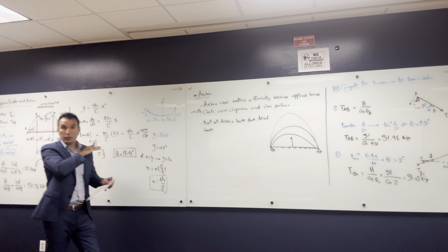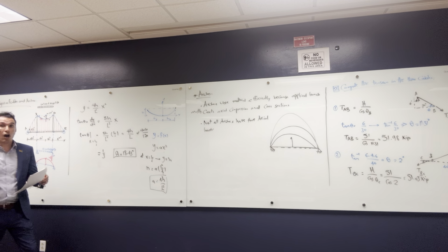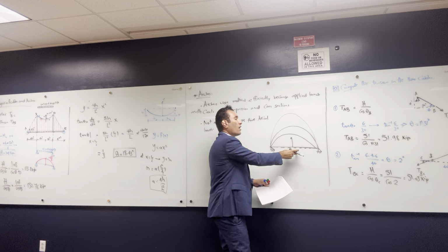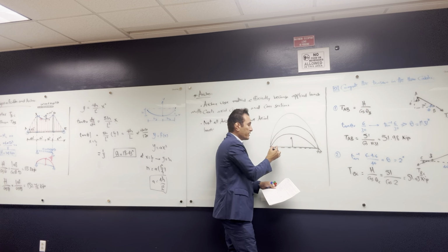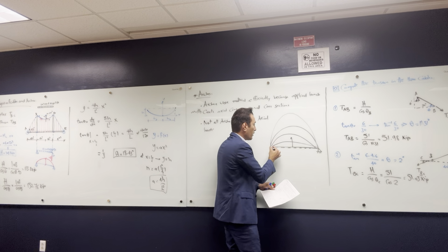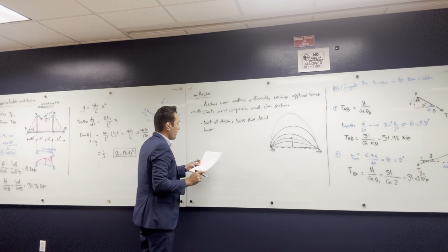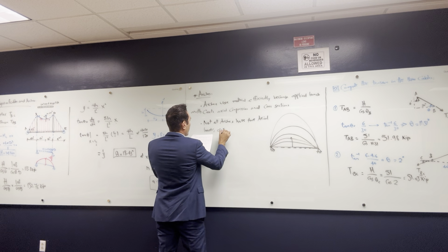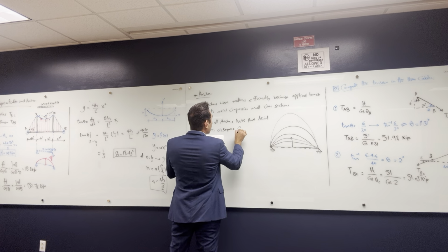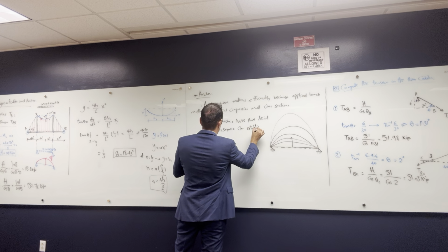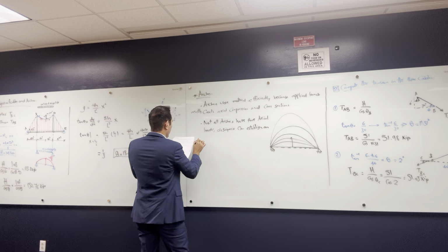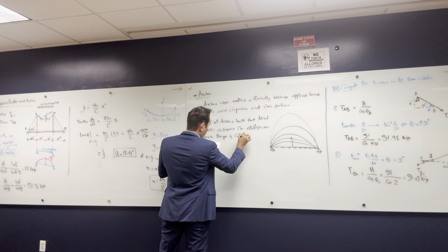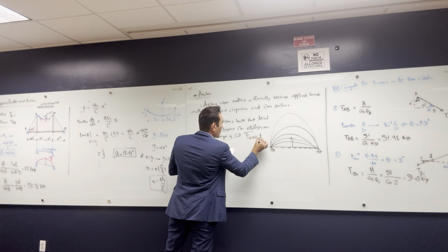So it's not like cables. Cables definitely are not gonna take any bending moment at all. Arches somehow can take bending moment, depending on the shape. So it can be and cannot be. Definitely not the same value of the bending moment of the beam. Once this is getting curved, it's taking less bending moment. The more curved it gets, the less bending moment it takes. Okay, so what I'm saying here, not all arches have pure axial loads. Designers can establish an arch shape called funicular shape.